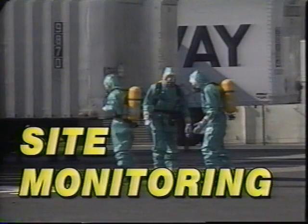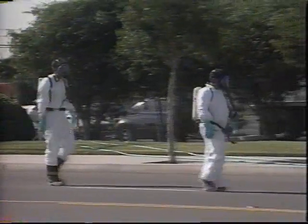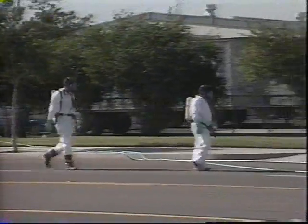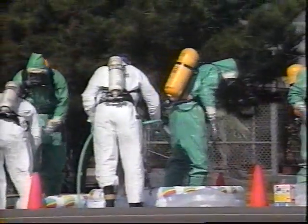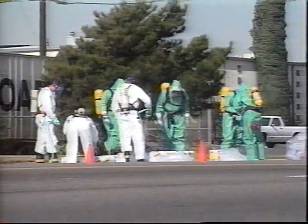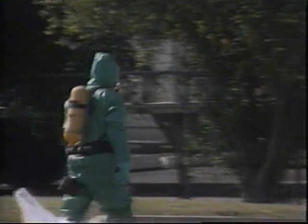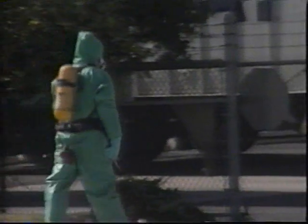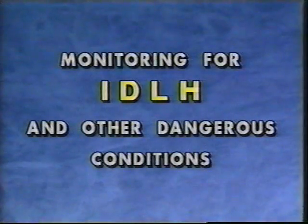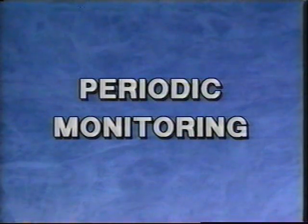Site monitoring. Priorities for air monitoring should be based on the information gathered during the initial site characterization. This information serves as the basis for selecting the appropriate monitoring equipment and personal protective equipment, or PPE, to use when conducting site monitoring. Depending on site conditions and project goals, 4 categories of site monitoring may be necessary. Monitoring for IDLH and other dangerous conditions, general on-site monitoring, perimeter monitoring, and periodic monitoring.